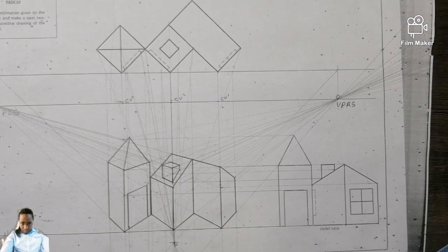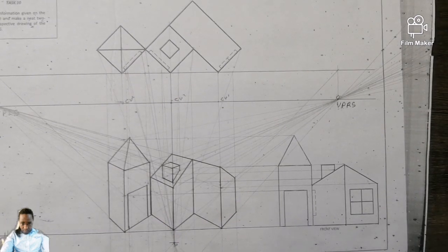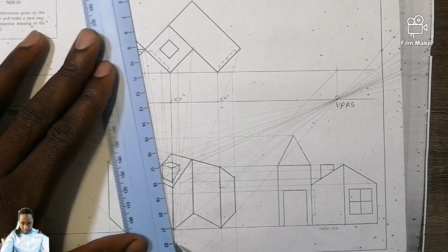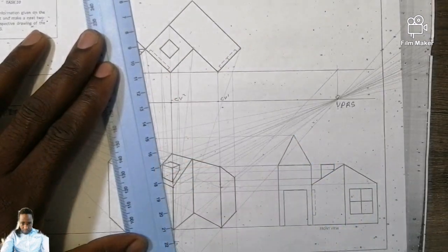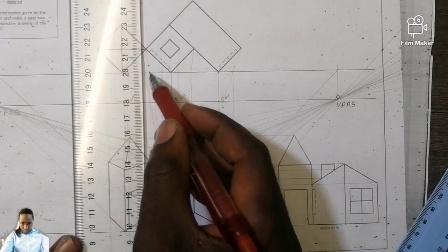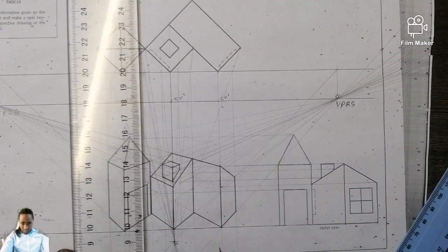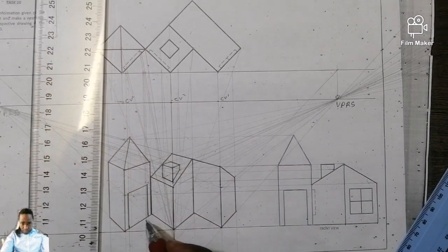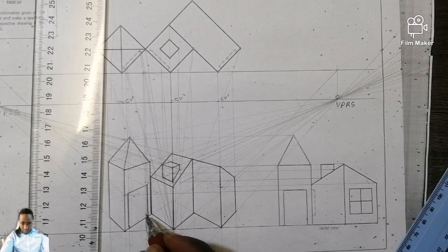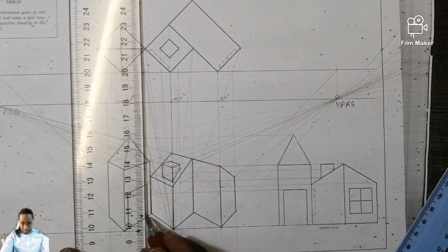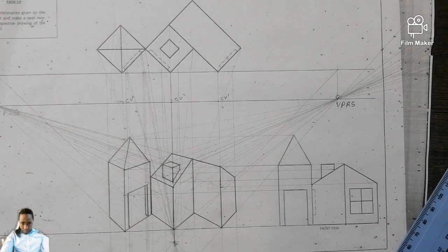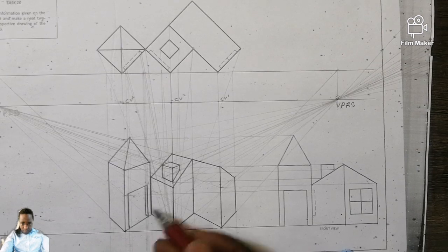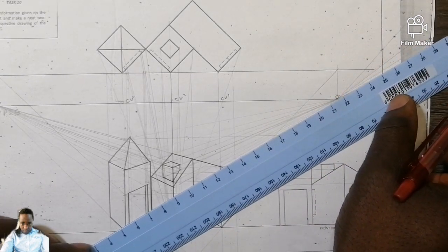So now we are going to show the thickness of the wall by taking that point to the stationary point. It goes from there vertically down. So which means it's dark from here till there and from here till there. That's the thickness of the wall. Then you take this point dark till somewhere there, directing this point to what? To the vanishing point of your right hand side.